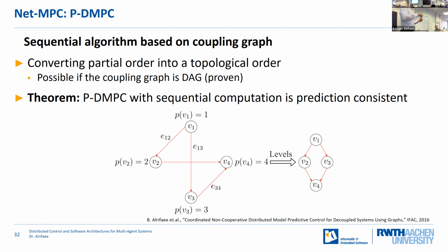So priority here is not the same priority, you know, from the rules of the road on the street. It is the computation order and not which agent is allowed to use the space. For doing so, the first agent will compute a trajectory, the second agent will avoid this trajectory, and then we will get to a solution.